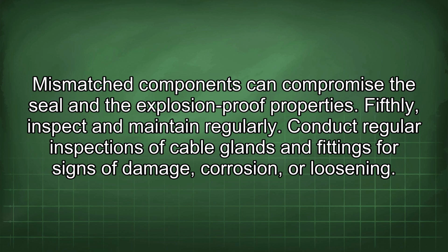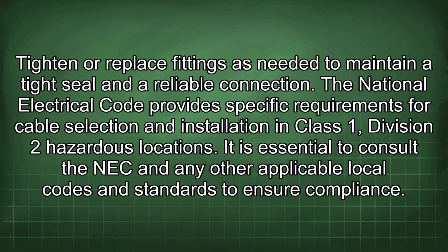Fifthly, inspect and maintain regularly. Conduct regular inspections of cable glands and fittings for signs of damage, corrosion, or loosening. Tighten or replace fittings as needed to maintain a tight seal and a reliable connection.